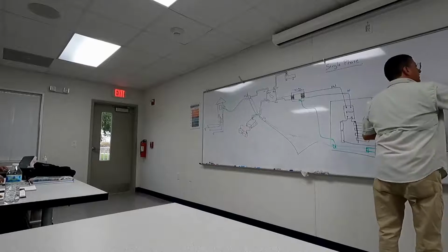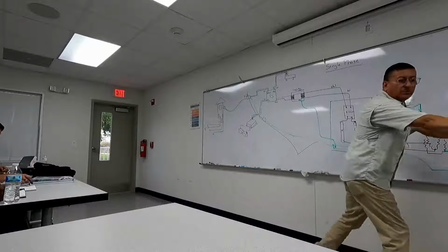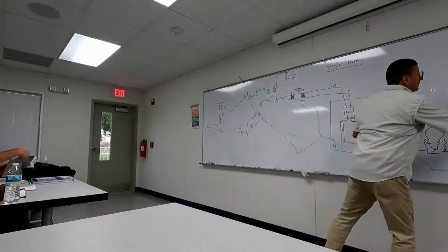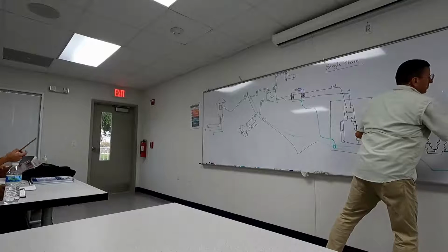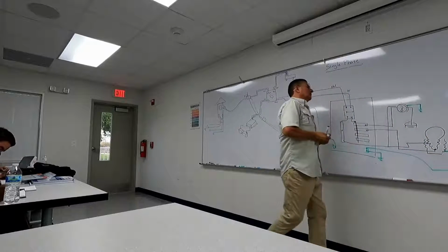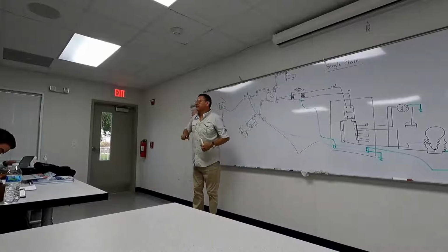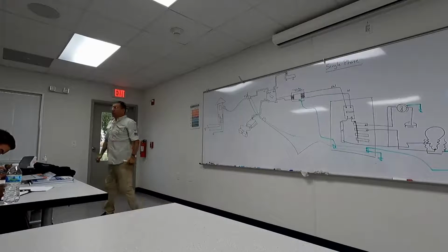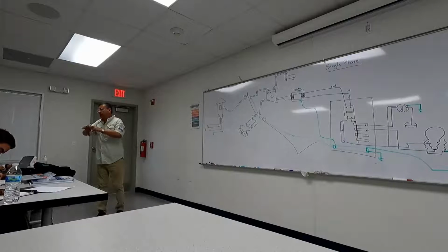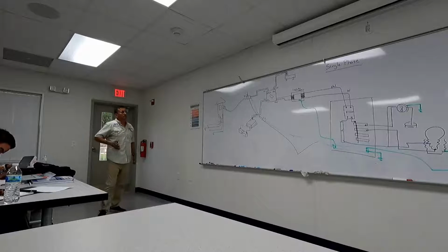That's the bonding conductor, and the bonding conductor is located on the stringers. High on the stringers, not in the water. That's correct. How do you attach it? With the ground screws. Every time you put a screw in a stringer, make sure you seal it.